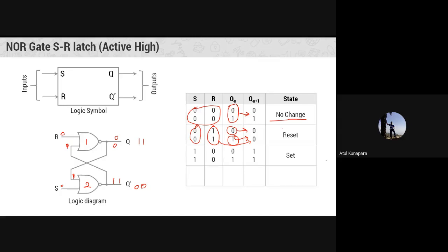So these are the three conditions of the latch at the output side of this SR latch, and that is going to be considered as a valid input combination and valid output state. But now for the last combination, that is when S and R both are equal to 1, 1. In that case, what will happen? If your Qn is equal to 0, your Qn plus 1 cannot be predicted. It can be 0 also, it can be 1 also.